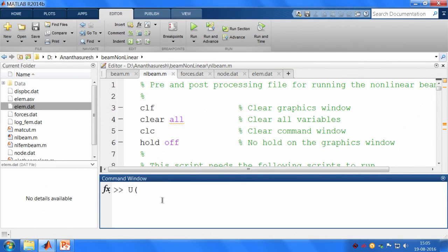So, if I look at U25, that will give me the displacement whatever 9.5313 10 power minus 5, right. If I put this as the first entry of the C matrix, I get that, and then I look at the U26, which is the y displacement of node 9, this 5.2712 10 power minus 12, I put that as second one and third one.